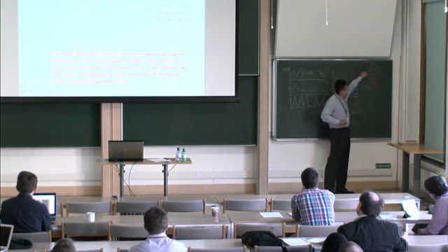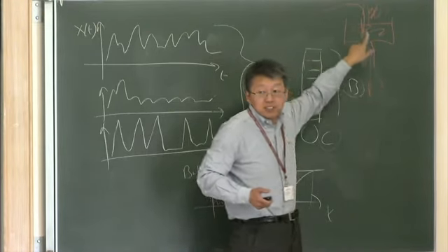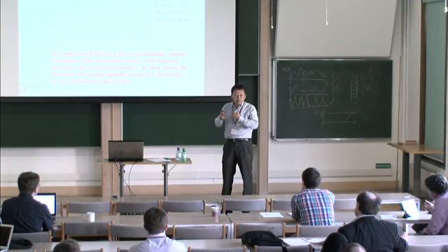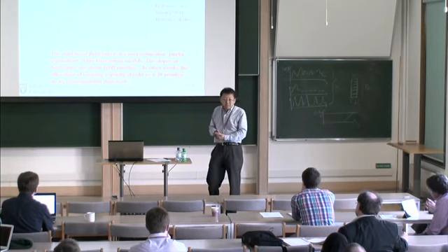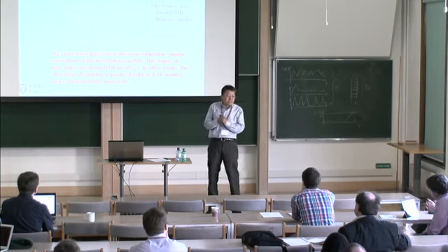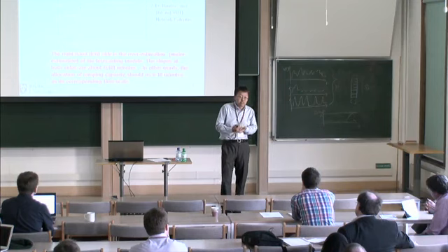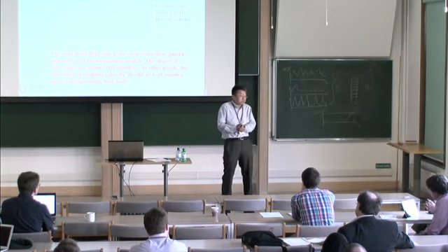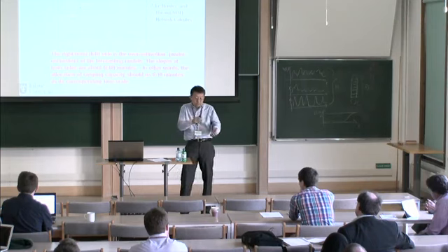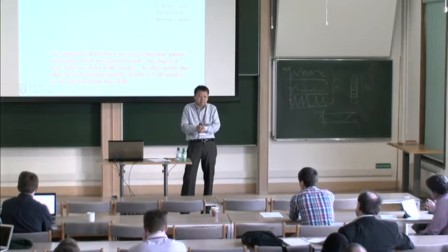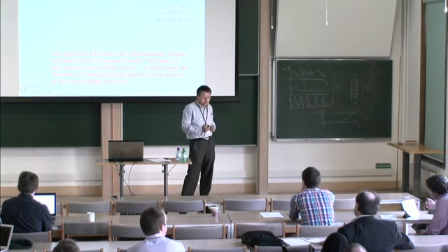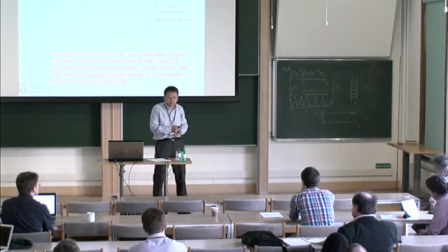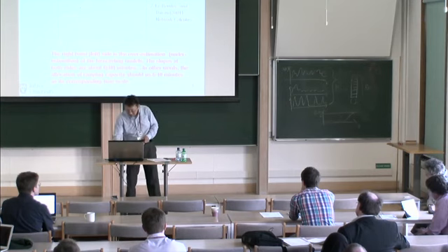the content. If you think of this as power and this as energy, essentially the storage to me is a capacity device, because it actually consumes net energy because of the efficiency loss. But the purpose is that I want to take care of the capacity issue by shifting the load, the energy, from time to time. In that sense, it's just like a virtual transmission line, but in the time domain instead of a physical domain. So that's why I echo a lot of Frank's drawing in the previous part.